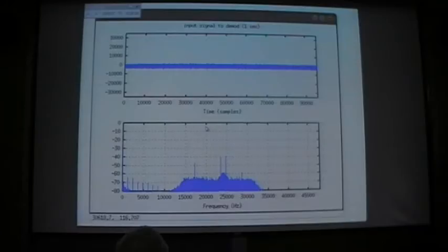So this is with the minimum detectable signal going into it, something like minus 135 dBm. And this trapezoidal shape is the crystal filter, amplifying the noise at the input of the radio through the IF chain. You can see how that falls off. That's just a regular FM radio type crystal filter that we use for adjacent channel selectivity.